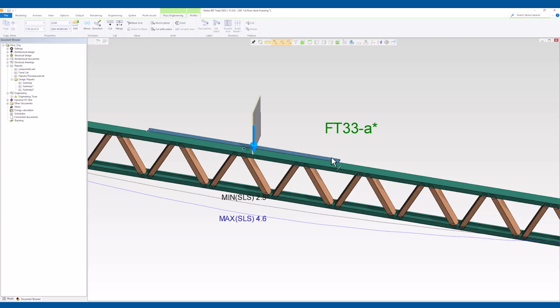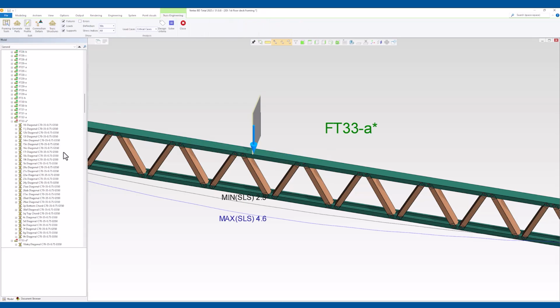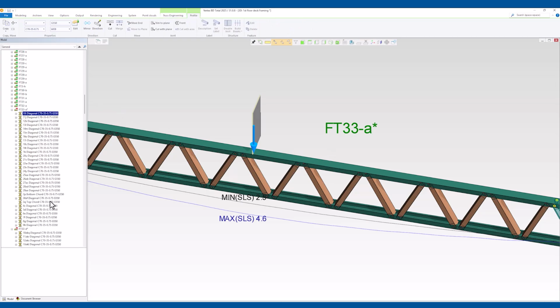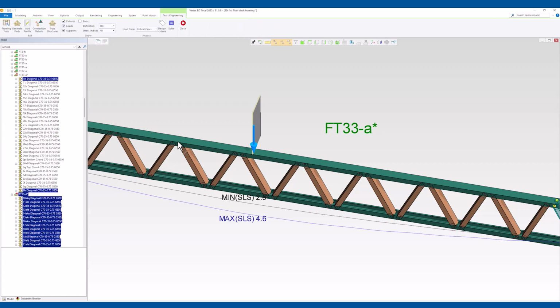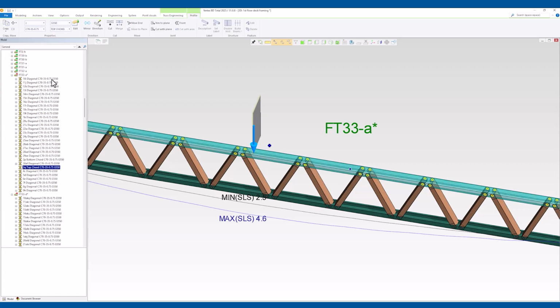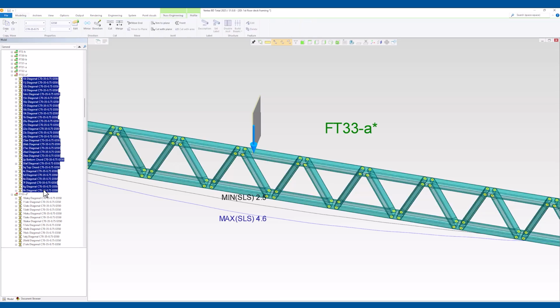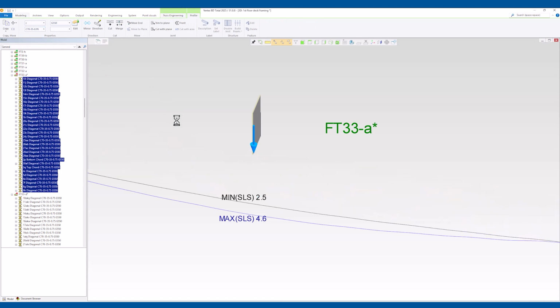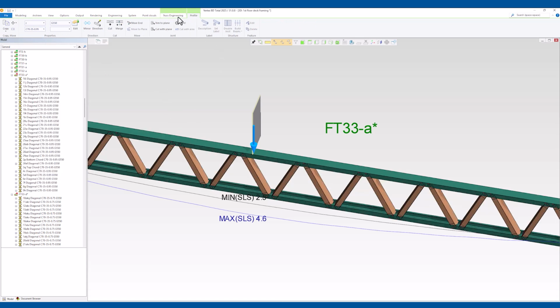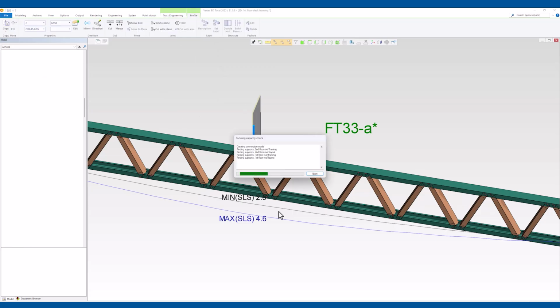And yeah, we can also try to, actually, I think we can just increase the thickness of the base material. Currently we're using 0.75, and yeah, if we select all the members of this truss and from this corner, we can just change the material thickness to 0.95 and click solve again.